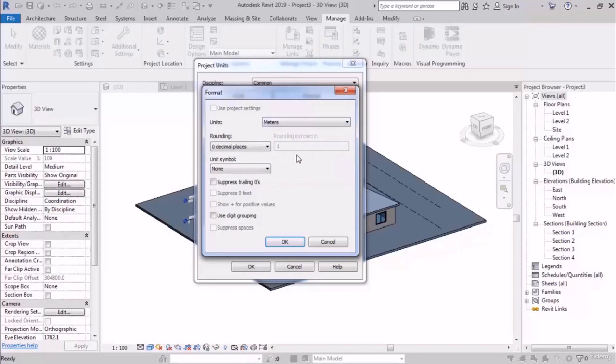And then we have a rounding part where you choose the number of decimal places. And pay attention, don't use the nearest options at all. Choose without a decimal, 1 decimal, 2 or 3. And I think the best answer could be 2 decimal places. Because it's for meters, it will be centimeters. And I think we don't need to be more accurate in architecture, so that's enough.